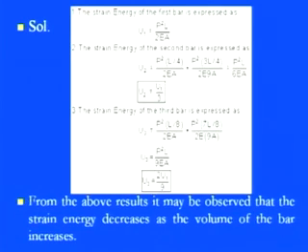Now come to the third case, in which only 1/8 of the length has diameter D and the other part is increased to diameter 3D. So 1/8 is there, and for the 7/8 the length has 3D diameter. Coming to the total strain energy for that case, we have U3, which is P squared divided by 2EA into L by 8.